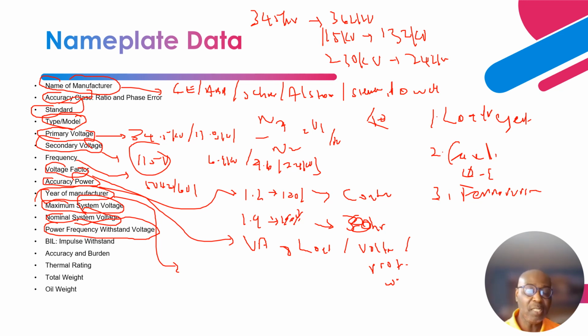So these passive network elements interact and can create resonating voltages. So that is what the ferroresonance phenomenon is all about. Okay, so all these conditions can create over voltage conditions, and the VT has to withstand that.